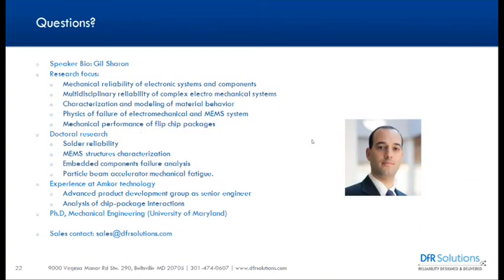Great. And next question. What parameters determine good underfill? Excellent question. The correct answer to any engineering question is it depends. So let me tell you what it depends on. If you're doing a BGA or a QFN, you're really trying to match the CTE of the underfill to the CTE of the solder, which is not impossible. It's doable.